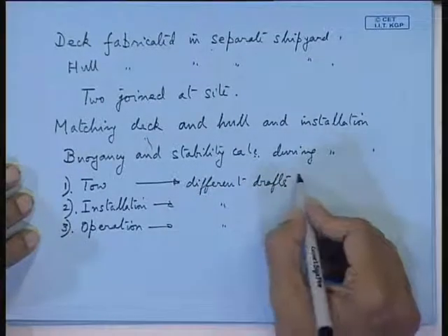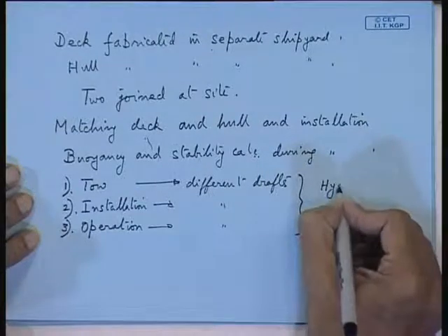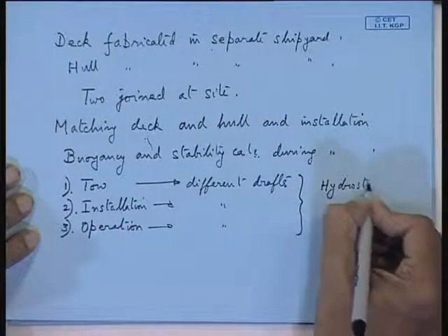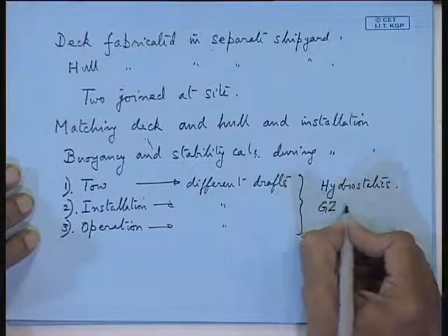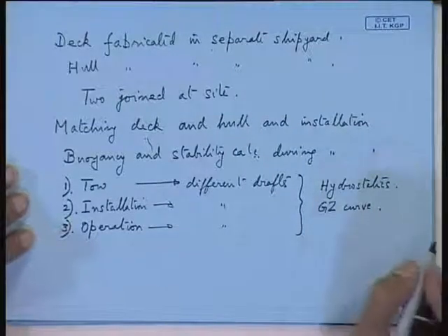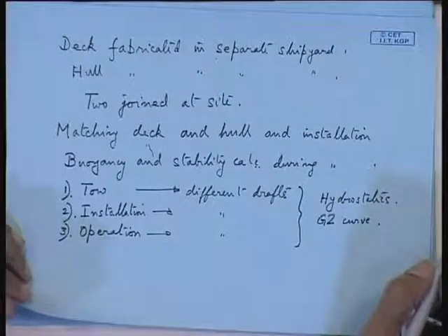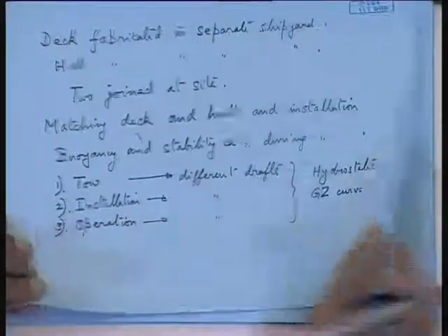You have to provide your hydrostatics and GZ curve. So, the buoyancy and stability part is over. Now, next comes the other part for the TLP, that is the hydrodynamic load.